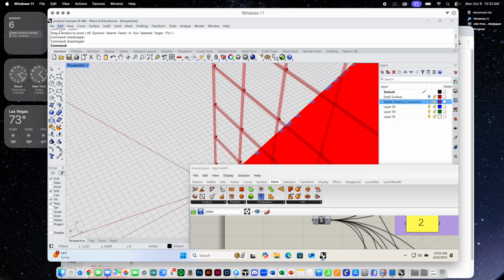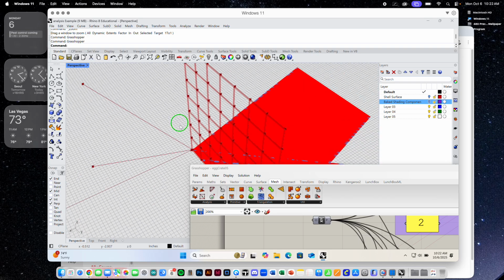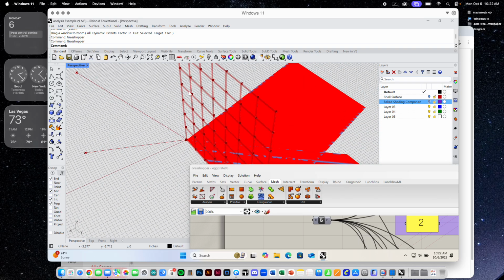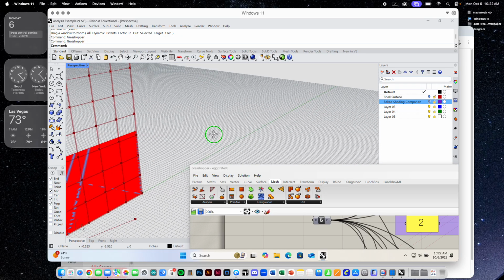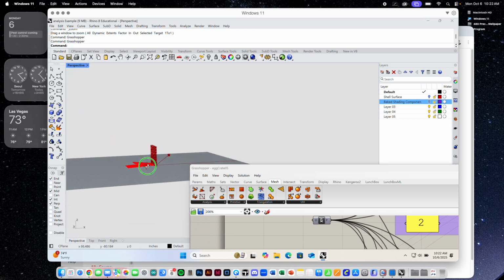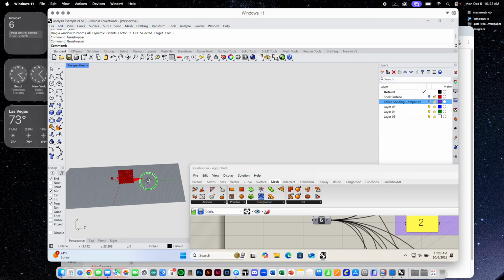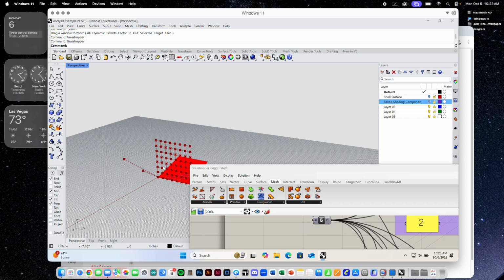But what I'm doing, or what I need to do, is figure out how to adjust, let's say, the depth and angle of these to sort of maximize the amount of shading for two different sun angle conditions. So I have this one and this one. You can see if I zoom out, I have two sort of coordinates in space sort of projecting light rays, right? So what I can do if I have, let's say, competing constraints, like I can know how to sort of adjust these things to shade for one direction of light. And then if I adjust it to shade for the other direction of light, then suddenly I'm letting more light into the first one, right? So I have competing constraints, right?